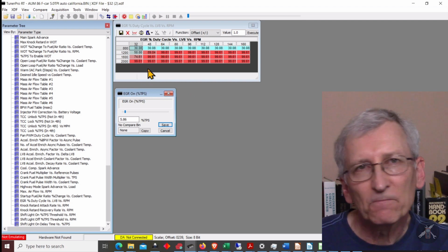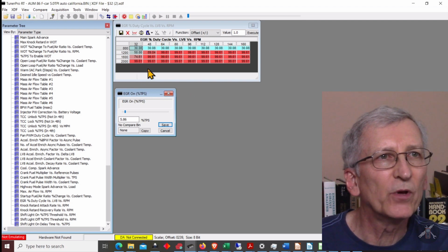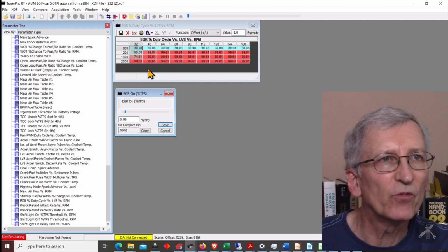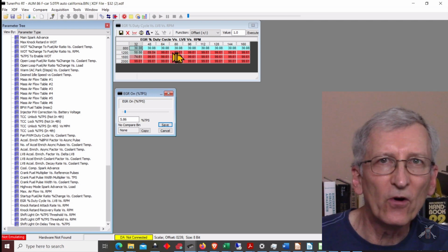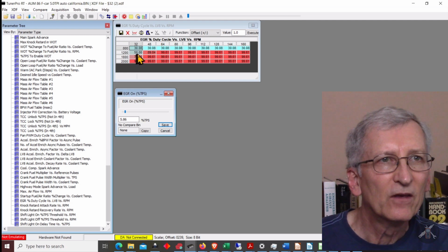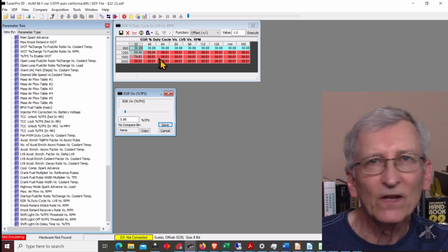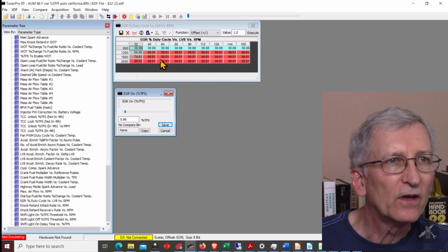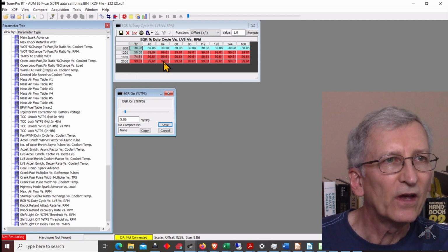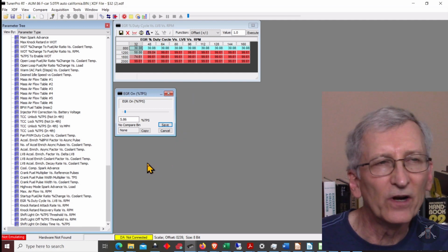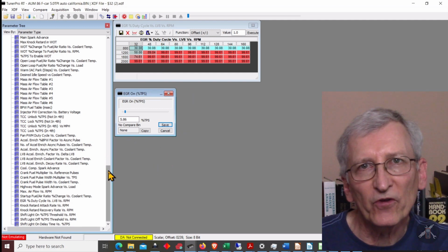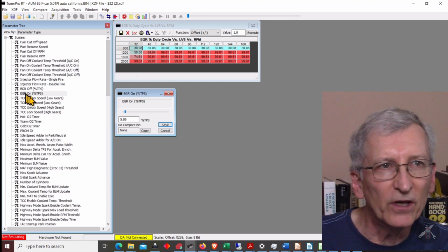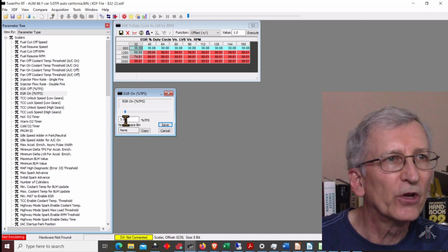Maybe because it's smaller, don't know, but you can see at 800 RPM, it'll start coming in at 30%, and it'll kind of ramp up, and then it'll go max. So it's a whole lot more aggressive than my car is, and it's only one model year newer. And this one only has a single value for EGR on or not on, and it's at 5.86 TPS. So at 6% throttle, you tip it in, it's going to start coming up.